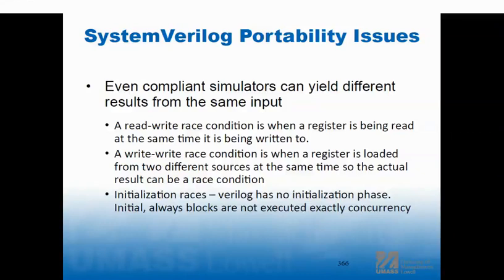But you have to know that, because that's the kind of thing that could work differently in behavioral code than in the physical design. If I have two things that write to the same location at the same time, who wins? Behavioral code might act differently than the actual device. Right? So that's the first two here. And don't think of this just as a memory thing, right? This could just be flip-flops that have this condition.